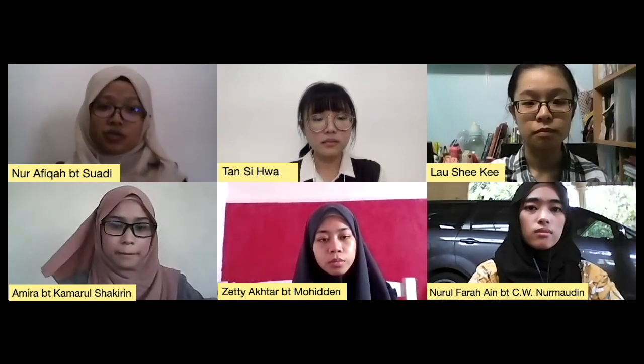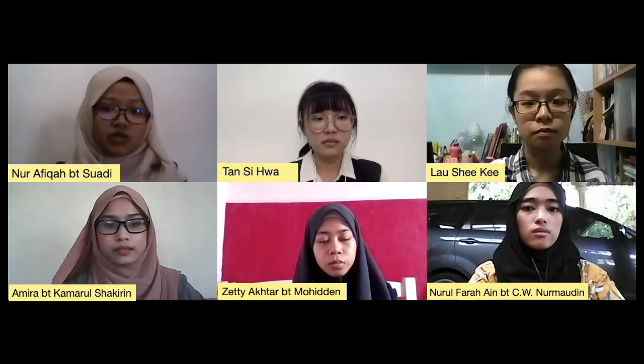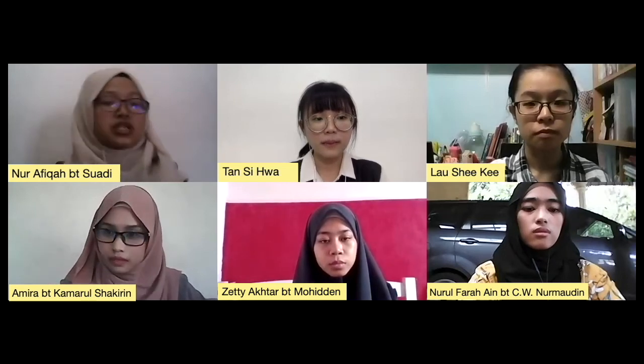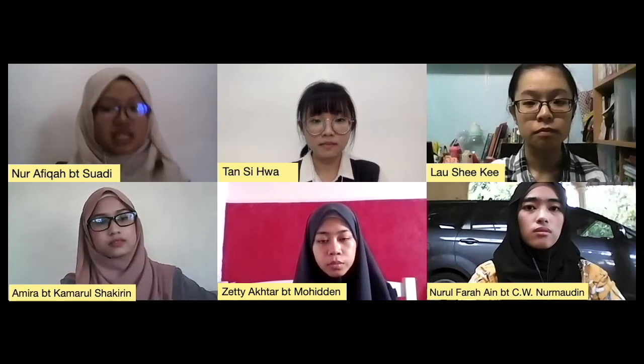Okay, sure, Amira. As you all know, our product is the pasteurized reconstituted milk. Thus, we have to determine the ratio between the milk powder and the water that we're going to use. I propose to use mass balance to calculate the ratio. As we agreed before, the milk product that we will use has 3.5% of milk fat content. And based on the fat analysis carried out for the full cream milk powder, we have 26% of milk fat.